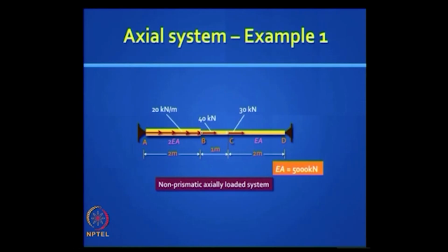The question asked is to get the complete force field and displacement field, which means find out all the unknowns, find out the support reactions obviously, find out the variation in the axial force, find out the variation in the displacement. Usually that is something not done in practice, so we are interested only in the maximum displacement if at all, okay. With that you know everything.